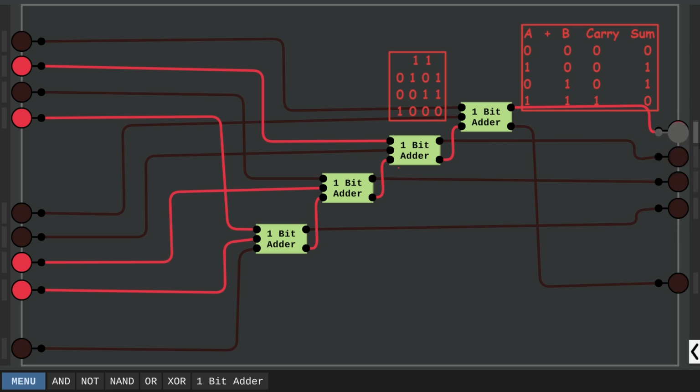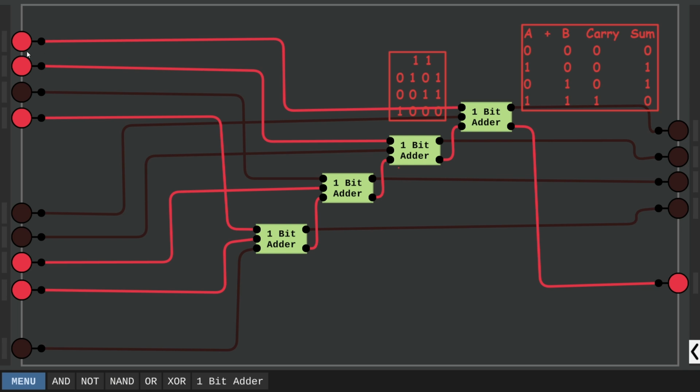So we can verify this by comparing its value to this table, which we know is working right. As you can see, if we add 1101 to 0011, it will turn on the carry bit, because the output of these two numbers is actually a 5-bit number, but this circuit can only show a 4-bit number. We can actually make an 8-bit adder by combining two 4-bit adders.